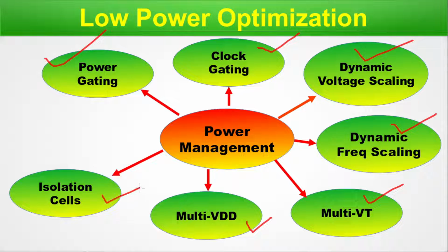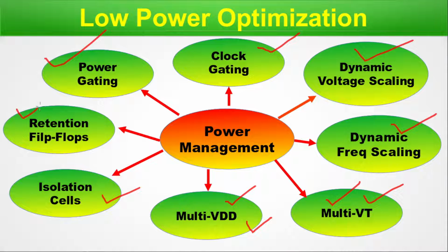And we use isolation cells to isolate different power domains inside the same chip, maybe with multiple VDD or multiple VT. Next, we use retention flip-flops to save the states before turning off the block and restore the states after turning on the block.